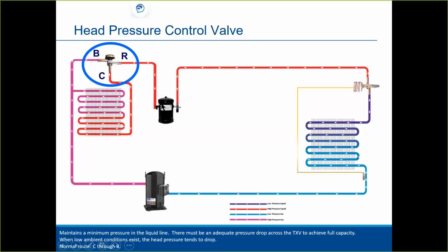Now, one would be thinking, well, this should be liquid refrigerant, but with the gas inside here in our receiver, it's saturated anyways, and it puts pressure on there, building up the pressure to be able to have a good pressure drop across our TXV. It also, when this gets shut down, starts to back up inside the condenser until you see where it starts to get purple here. So it matches what's going on with the system and the outdoor temperature. So your coil gets a lot smaller, in other words. We're rejecting a lot less heat.